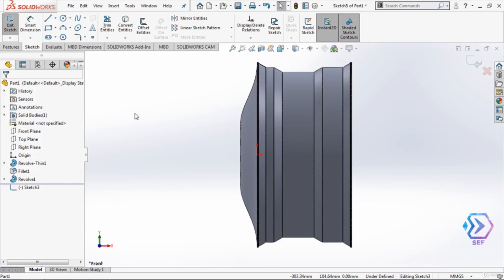It's because you will have a lot of problems if you use the cut revolve. I did that before and I had a lot of problems. As you can see here on the video, the last cut extrude was really bad and I didn't know how to deal with it. It's a big problem because I used the wrong features to get the form that I need. So in order to avoid any problem, the combine is the solution. So here let's first get the form of the revolved base that we are going to subtract from the wheel, and after that we will see how to use the combine.